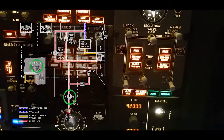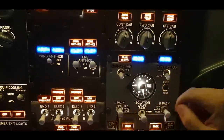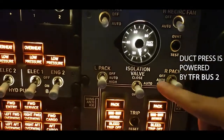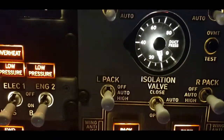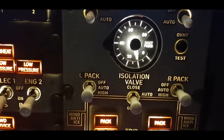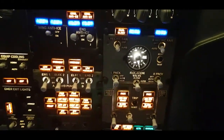The bleed air duct pressure indicator, as you can see here, shows the bleed air pressures for the left and the right ducts. Here you probably cannot see the right one, but we have two needles here, one for the left side and the other one for the right side. All of the bleed air valves are of a butterfly type. That means that they open and close quickly.